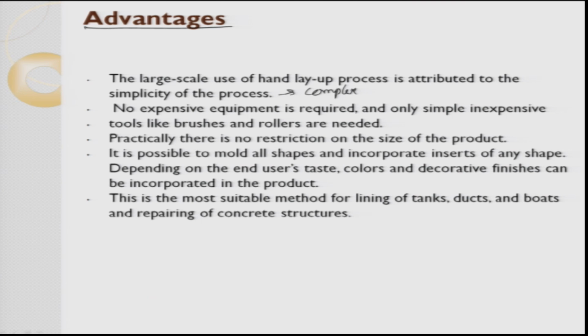It is a very non-expensive process because there is no equipment which is required. All you need is only a pattern. Then all the other things are brush and rollers and very trivial items. Practically there is no restriction on the size of the product. That is the biggest advantage of this. Big structures, very big structures, where it does not have structural applications, only if giving form, it can be used.